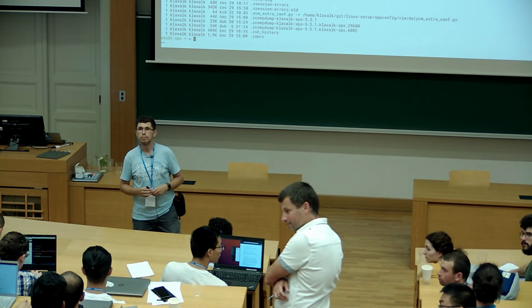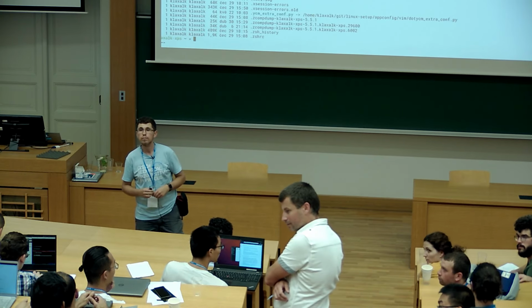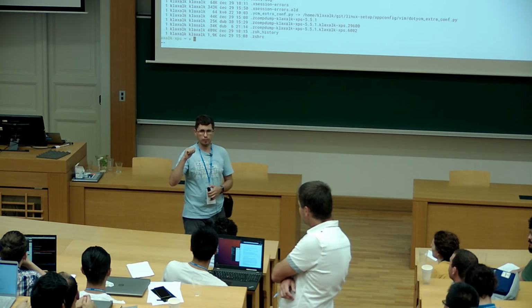I have a quick question about the SLAM. You mentioned that you are using it, but are you using it just for odometry, or do you actually use collaborative SLAM, where all agents are cooperating and you are doing your planning on partial maps? Or the map is known and this is just for localization? So currently our experience with onboard SLAM is only with a single drone.